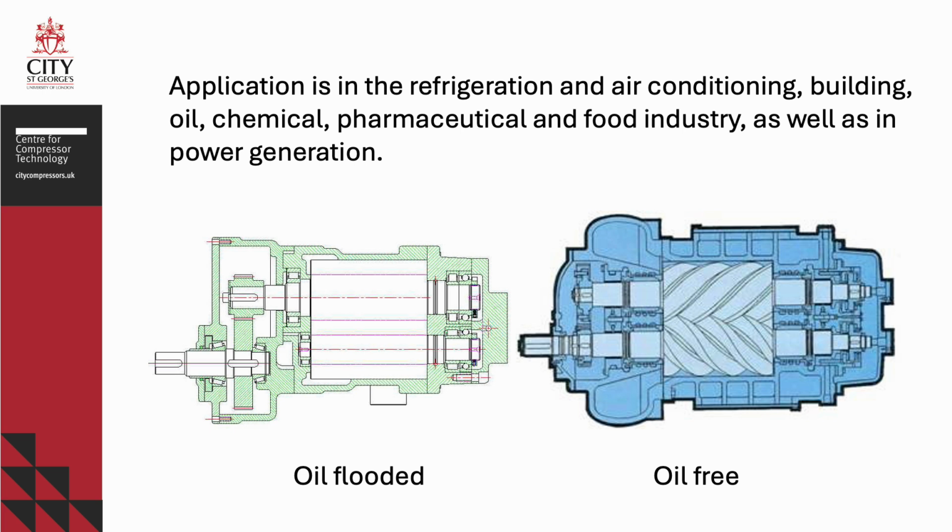Due to high pressure forces acting upon the screw compressor rotors, a high number of strong bearings needs to be used. Nine in total in the compressor presented on the left. Since the working chamber of the dry screw compressor presented on the right needs to be separated from the gears and the bearings, otherwise lubricated by oil, 8 seals need to be utilized, all to the satisfaction of the bearing and seal industry.